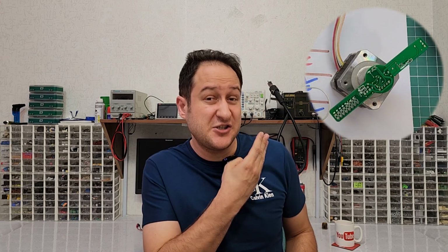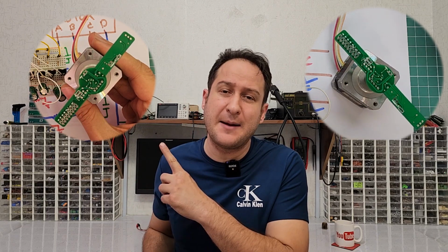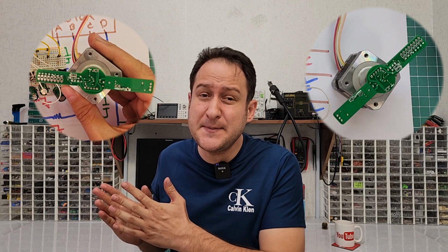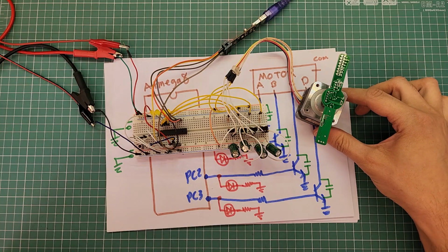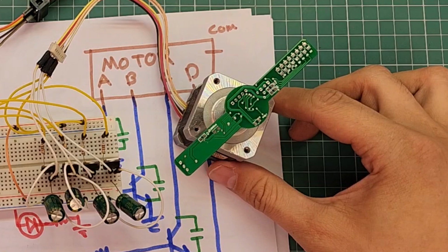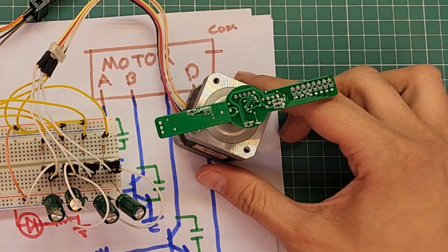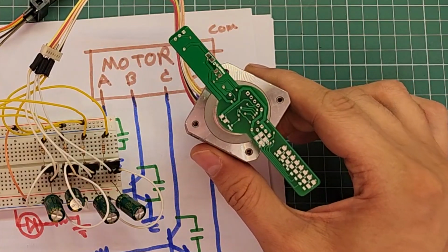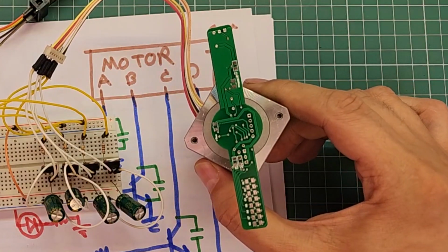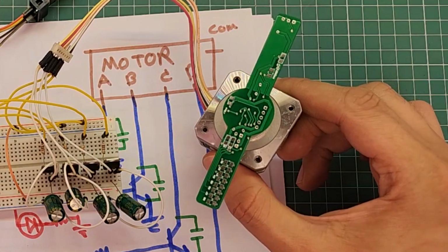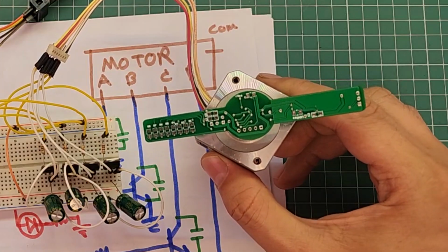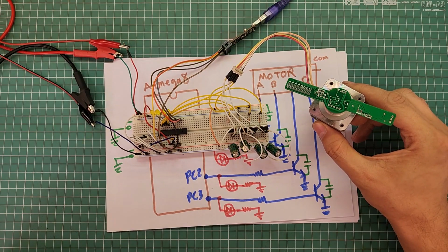This is the movement of the shaft before applying microstepping, and this is the movement of the shaft after applying microstepping. This is a bit softer than before, but it is still unacceptable. What is the problem? This is happening because the force produced by the winding is not linear. I mean the amount of force the winding produces at 80% duty cycle is not 4 times bigger than the force produced by the same winding at 20% duty cycle. They are extremely different, and this fact causes high stiffness for the shaft at the main step points.